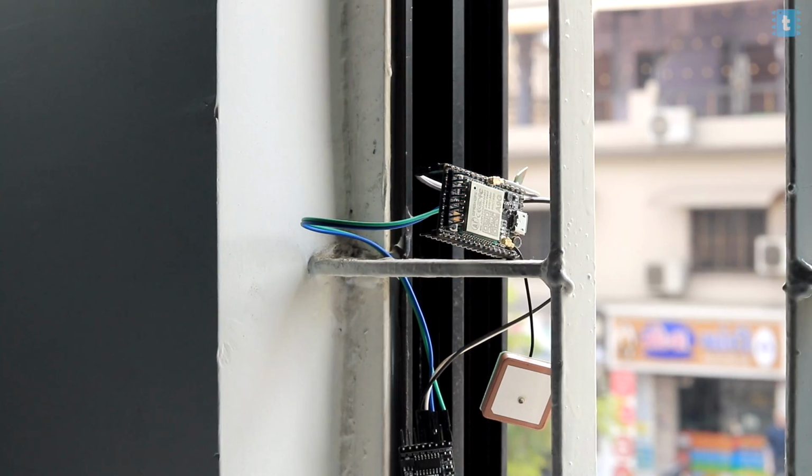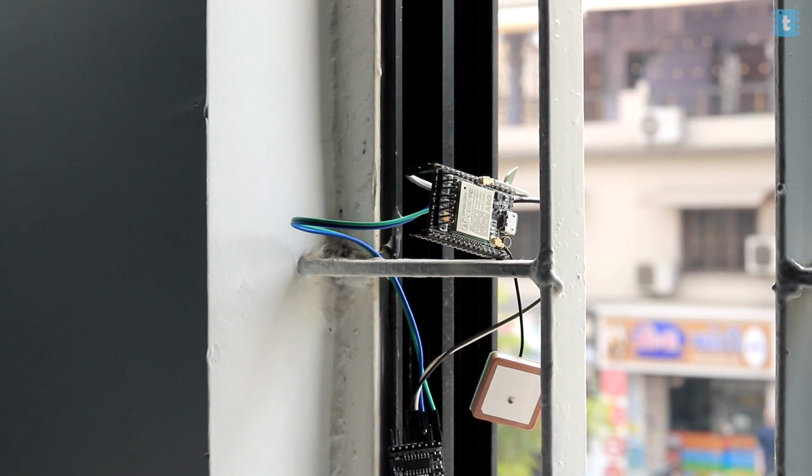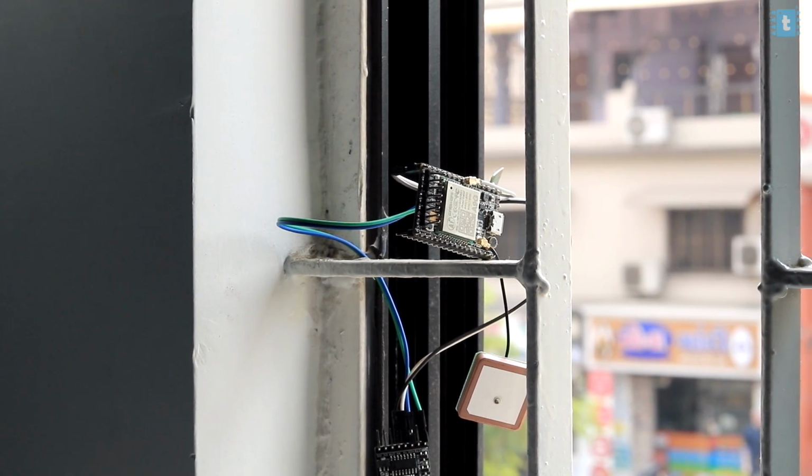Now let's do one more thing, which is to test out the GPS connectivity. Let's try to get the GPS coordinates on the A9G board, and let's see the script for it. But before that, we need to move to a window location so that this A9G board can get proper GPS connectivity. Right now I'm sitting near the window where I have put the A9G board outside the window so that it can get some GPS satellite connectivity.